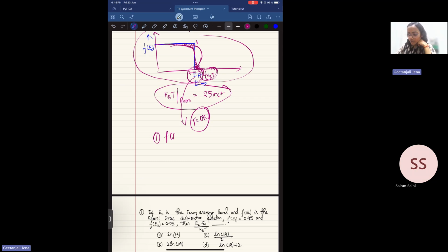This is given by the Fermi Dirac statistics. We also need to see whether there are empty states in the system so that carriers can flow easily from the source to the drain, and whether there are available states on the source and drain side. The other thing not considered is the importance of the contact interface.